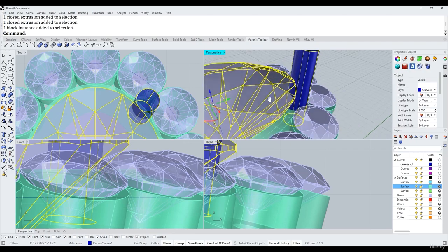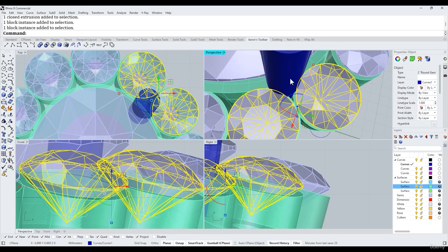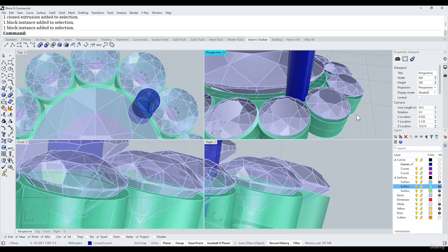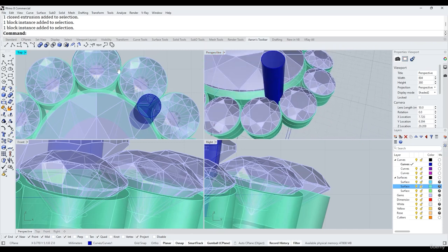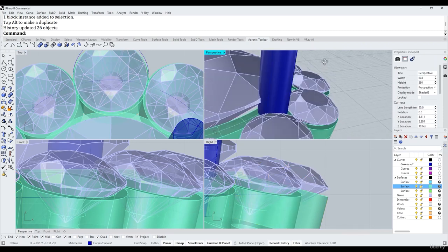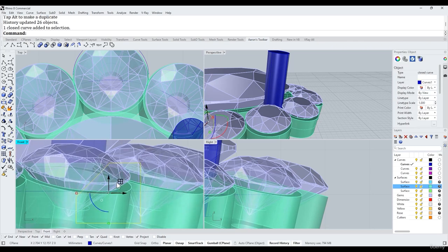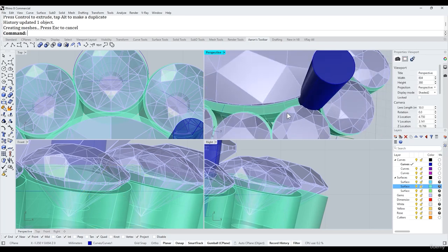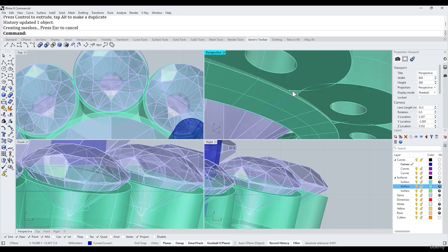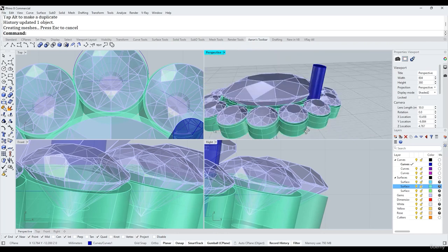So I'm looking for a nice little bite of the center gem into that claw. I also want this claw to overlap these two gems here a little bit, because those are going to sort of nip into that claw. That's what's going to hold them in place. I can also move my parent gem and underbezel in slightly just to increase that overlap there. I'm also going to make a slight adjustment to our underbezel for our center gem. I just want to move that down a touch. And you can see I've also got a step underneath here, so I can turn on my control points and just move that up slightly so it's a bit smoother there.